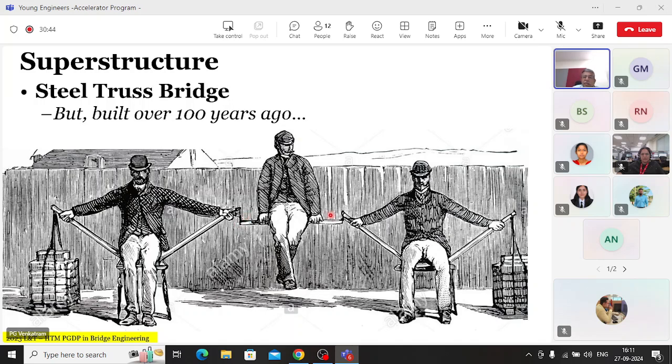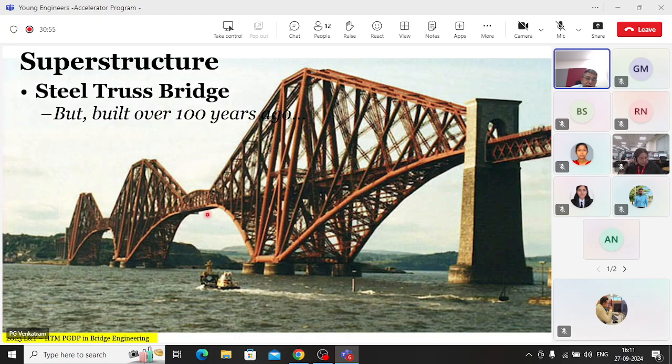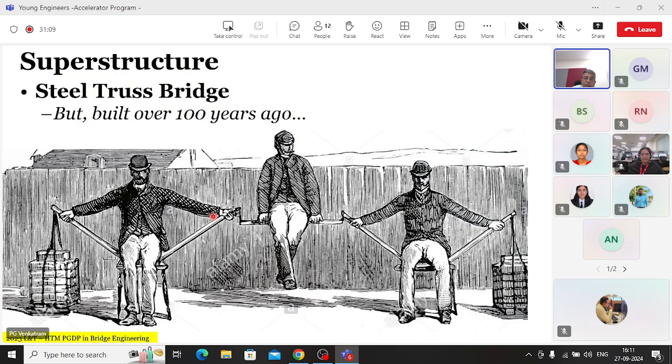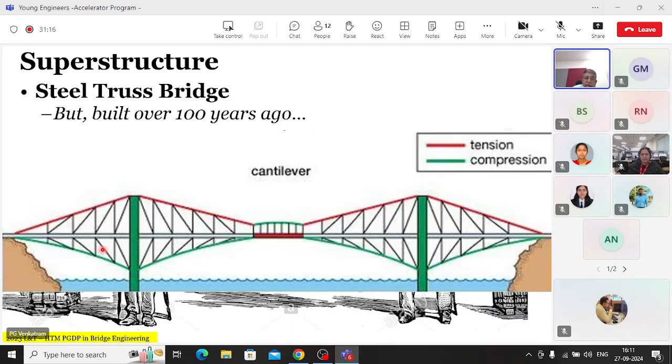To an extent. That is why, if you look at the olden days, they would try to minimize the suspended span. If you want to see an example of it, if you take this bridge, it's much smaller than that. But if this becomes too small, I can show you a few examples where this has been reduced to 5 meters and 4 meters, and there we have a serious vibrational problem. So it cannot be too small, but it also depends upon that. And that's where this counterweight magnitude is decided upon.